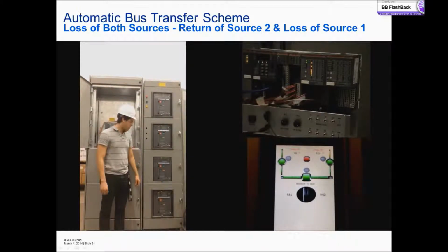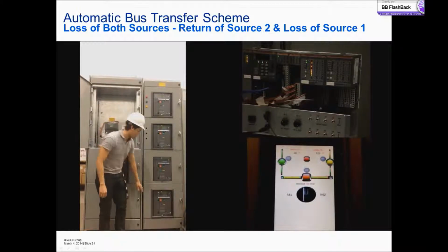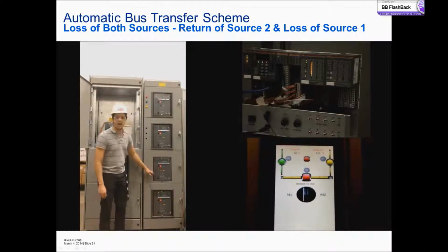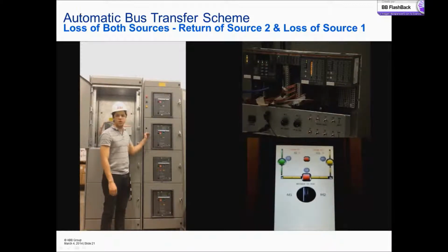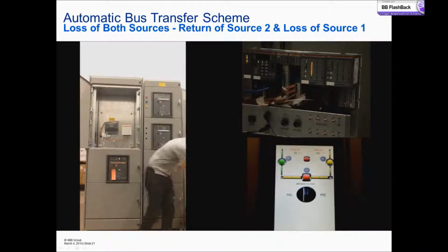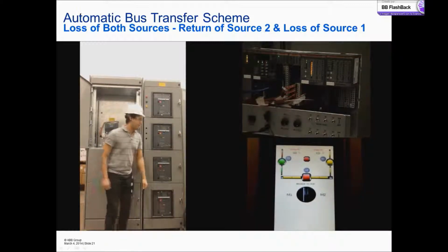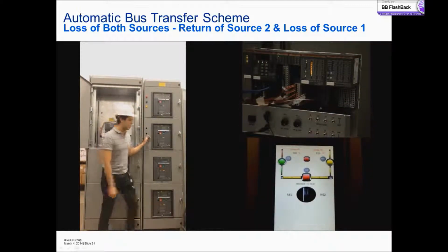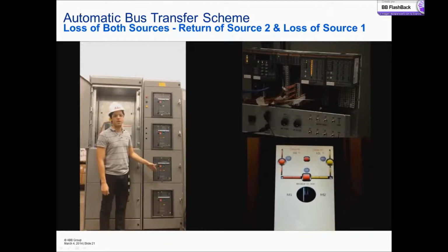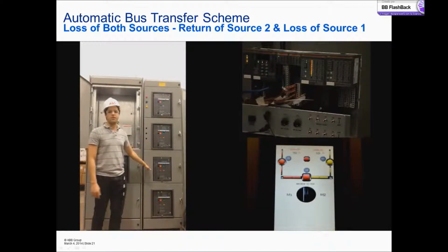It waits 10 seconds. It closes, and the tie also closes. And this one remains closed because there is no voltage in it. So we return the voltage, and it closes, parallelism, and then we have normal conditions again. So this one will open after 5 seconds.